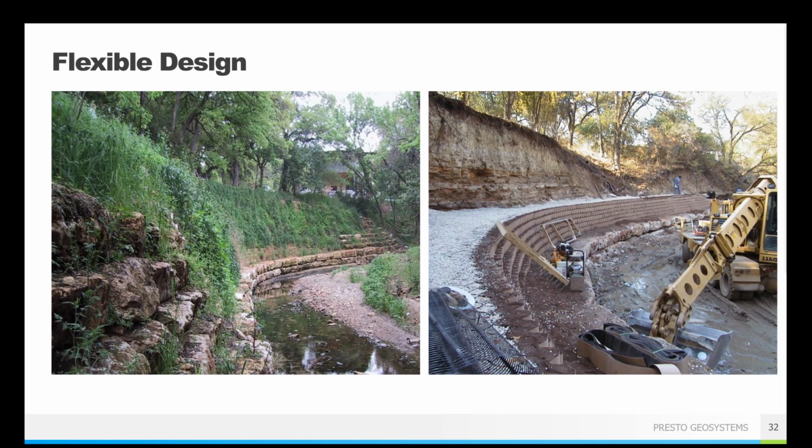In this case, they put concrete down in the lower tiers and then vegetation above that. And the concrete in this case was because they were going to have active water flow. This was a channel, a stormwater diversion channel, actually. So it was moving water at a relatively high clip, moving around this corner.